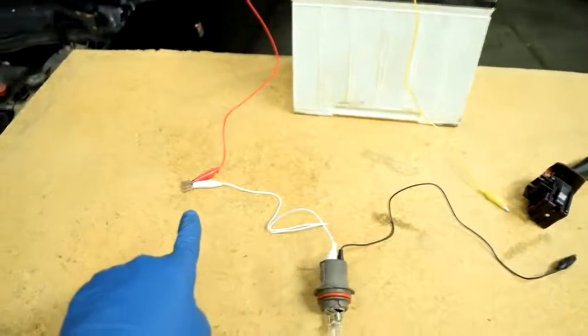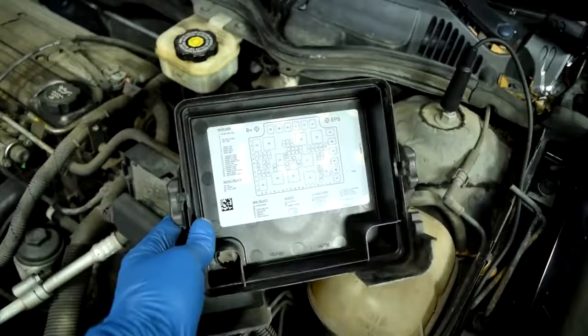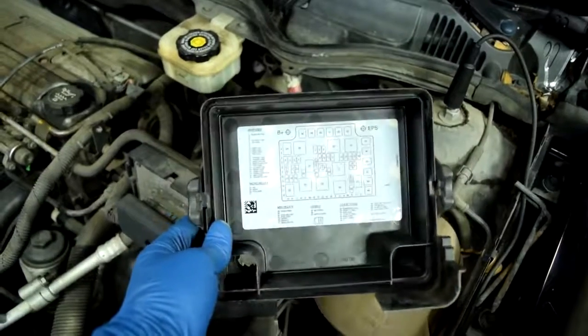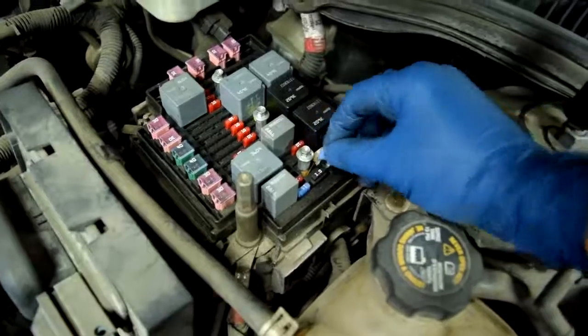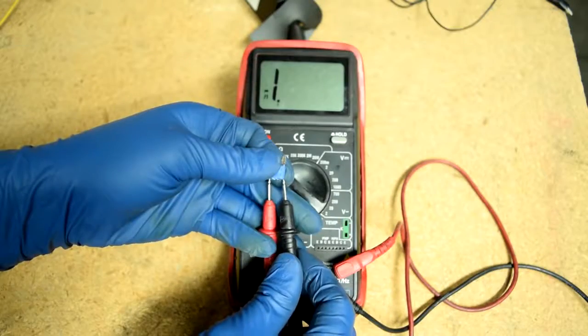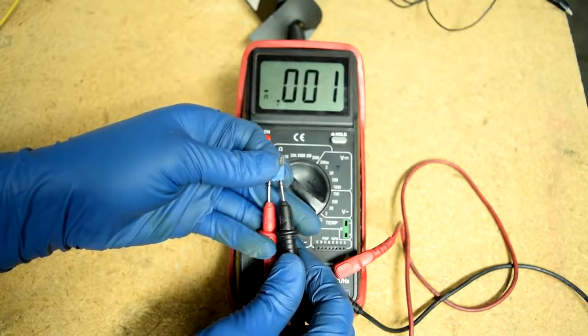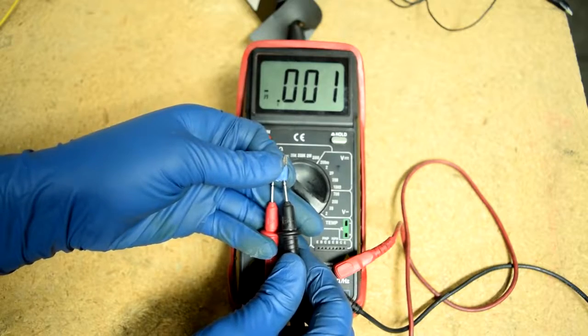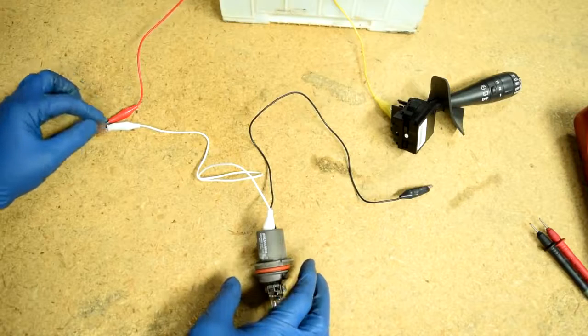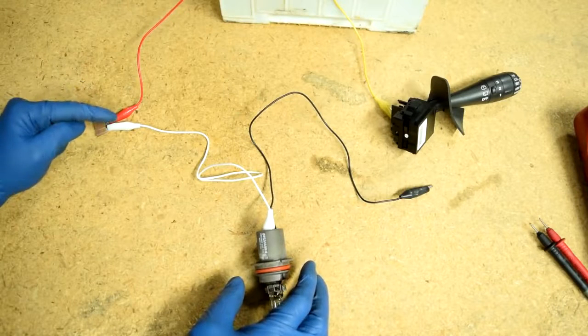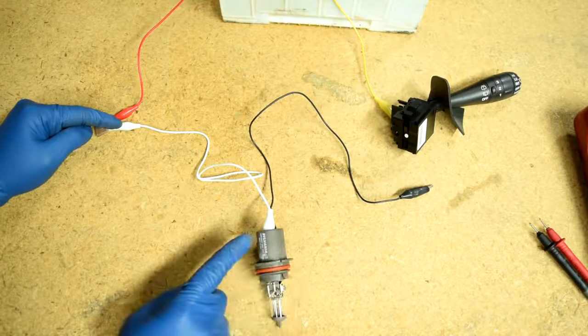Alright, so the easiest thing that we can check on this circuit if we're checking for an open circuit is to obviously check our fuse. So go to your fuse box under the hood, look up the correct fuse for your headlights, and then you can remove the fuse for a close visual inspection. And you can of course do a continuity test to make sure. Just make sure you're not doing a continuity or a resistance test on a hot circuit. Next, what you can do since you're already here is to check for continuity from the wire that goes from your fuse to your light bulb.